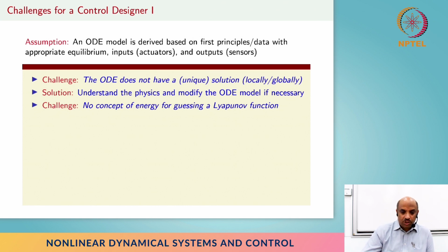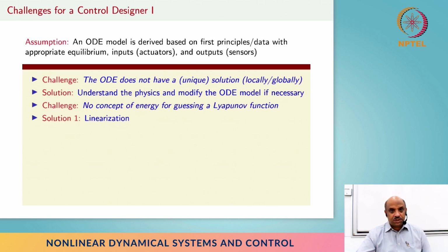and the biggest difficulty of, in one sense, basically we don't have a choice but to understand Lyapunov stability, because nonlinear system behavior, if you want to talk about some good behavior, then Lyapunov stability is one of the best things that we can think of, some kind of perturbation from an equilibrium, how it behaves after that. And then through this very intuitive idea of energy, we developed this theory of Lyapunov function. Lyapunov did, okay?